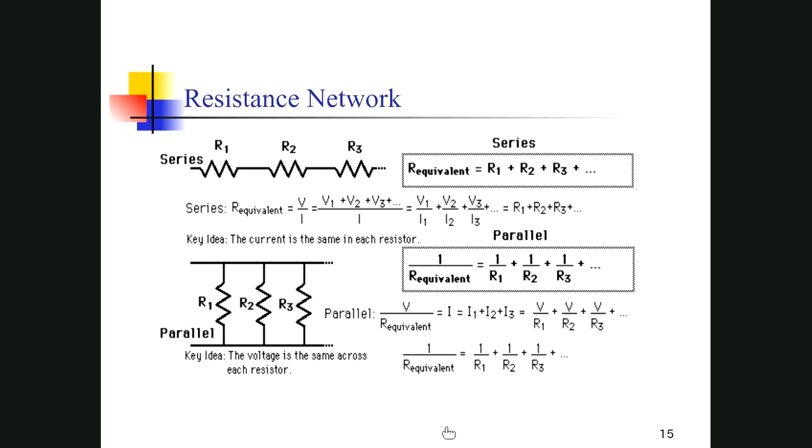Now, networks of resistance. We take a quick look at resistance. In practice, we may have several loads in series. When you have several loads in series, namely R1, R2, R3 in series, they share the same current. They have the same current, and they share the total voltage.